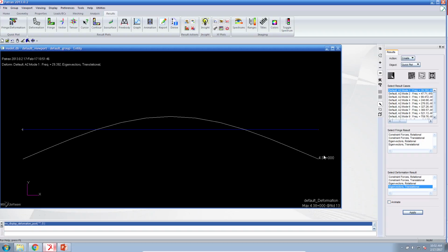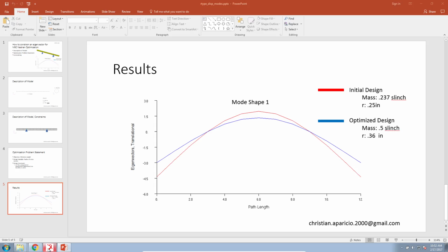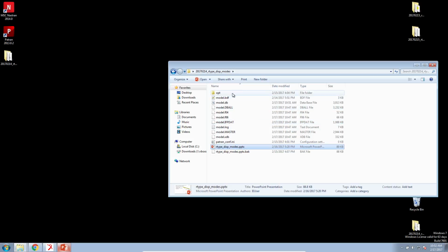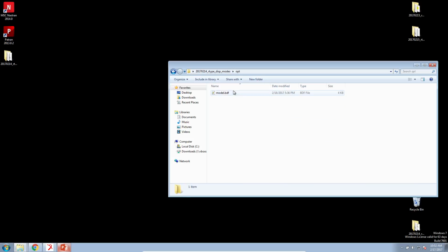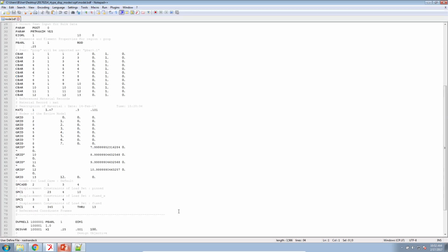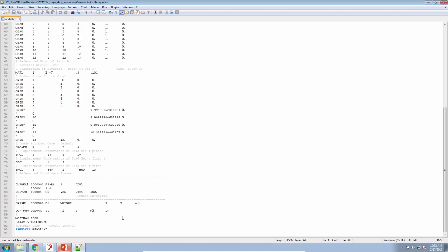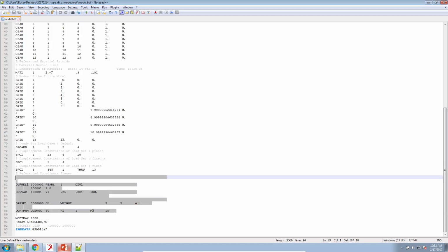We're going to impose a constraint at this tip, which is node 13, that says the relative displacement at node 13 for mode 1 is to be within -3 or +3. So let's go ahead and walk you through the process. I already constructed most of the design model, so my objective, my design variable is already included in this input file. I just have to create my constraint.